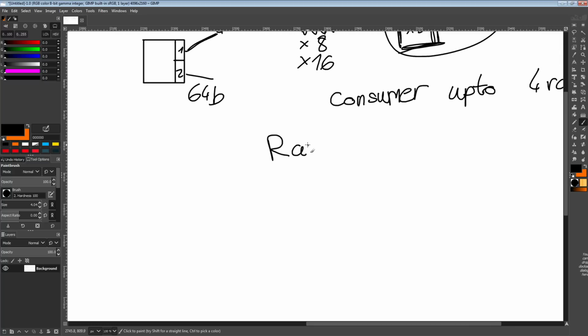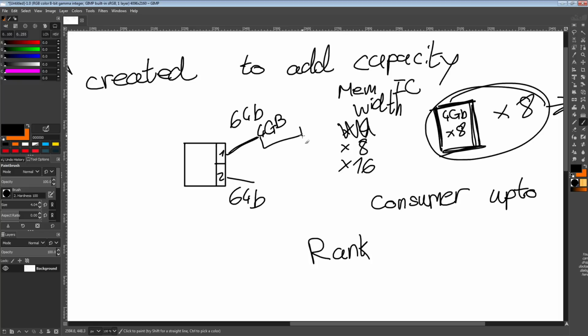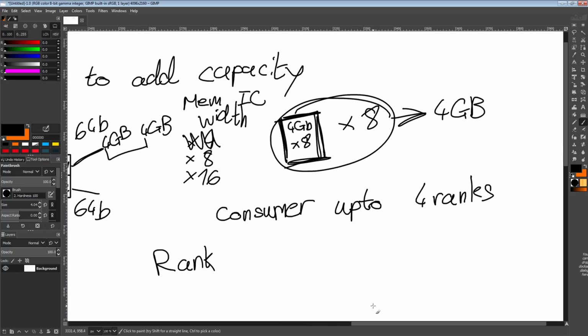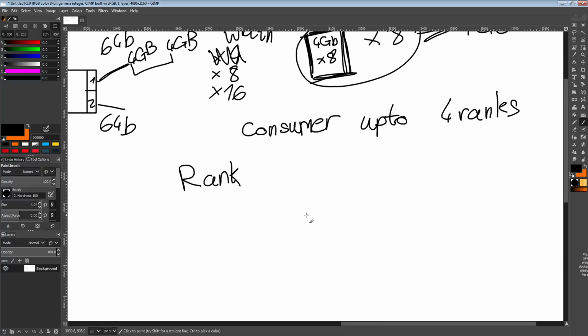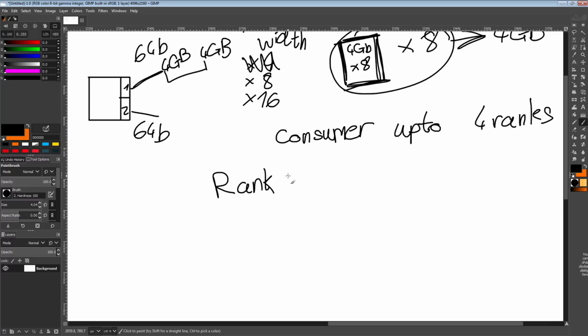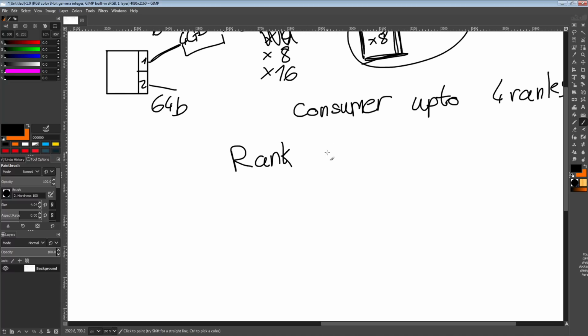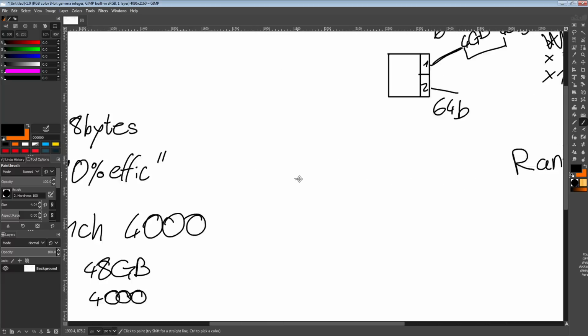So the CPU manufacturers were like, well, these wires just go to every single rank, ultimately. All the ranks share the same set of wires. That's part of why you can only go up to 4 of them, because if you keep adding them, the wires start getting too long, and it starts causing issues. But the CPU vendors basically were like, well, if the wires are unused, but we have a whole second group of memory, let's say you have a dual rank setup. Well, you have rank 1 and rank 2, and the wires are not being used by rank 1, right? Let's say you're trying to read something from rank 1 and it's not ready to do that just yet. Well, you could just write or read something from rank 2 while you're waiting for rank 1 to do whatever it's doing. And that's called rank interleaving, and it basically